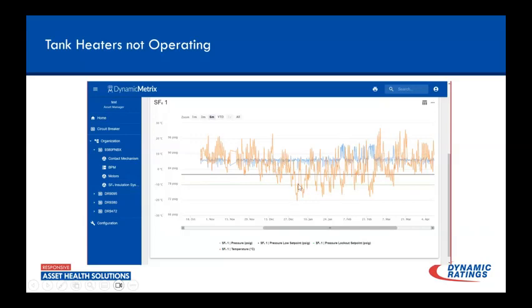But we can see as we go through, when we start seeing these sub negative 10 degree drops in temperature, we usually see it followed directly by about a 7 or 8 PSI drop in our gas pressure on almost all of these big drops. We're seeing this peak come down. So not a huge deal, however, because the breaker was pressurized to the point it was.